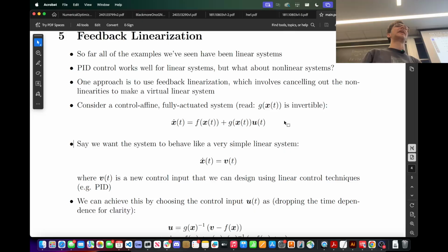So at a high level we can compare what we actually observed the vehicle do, like the real acceleration, to the predicted acceleration with the current dynamics parameters, and then try to update the parameters such that they match reality, if that makes sense.